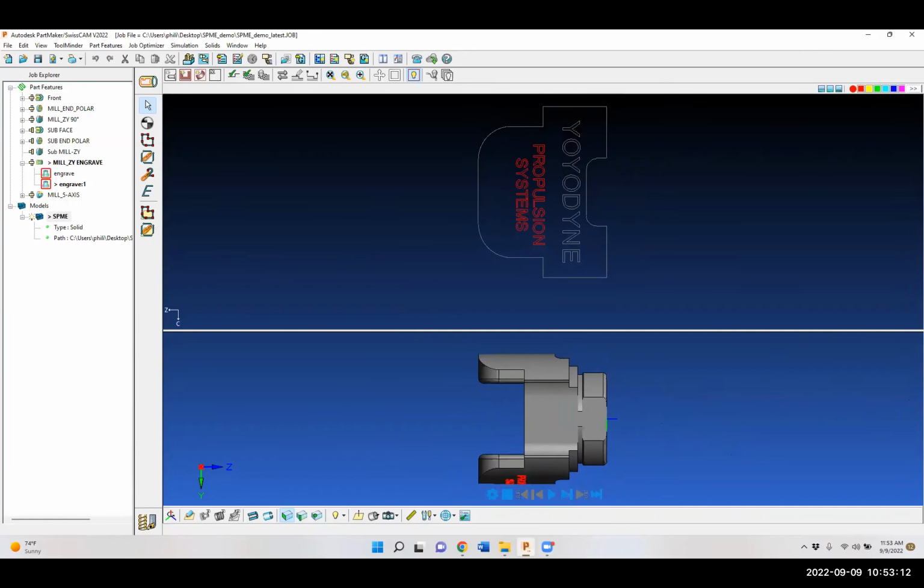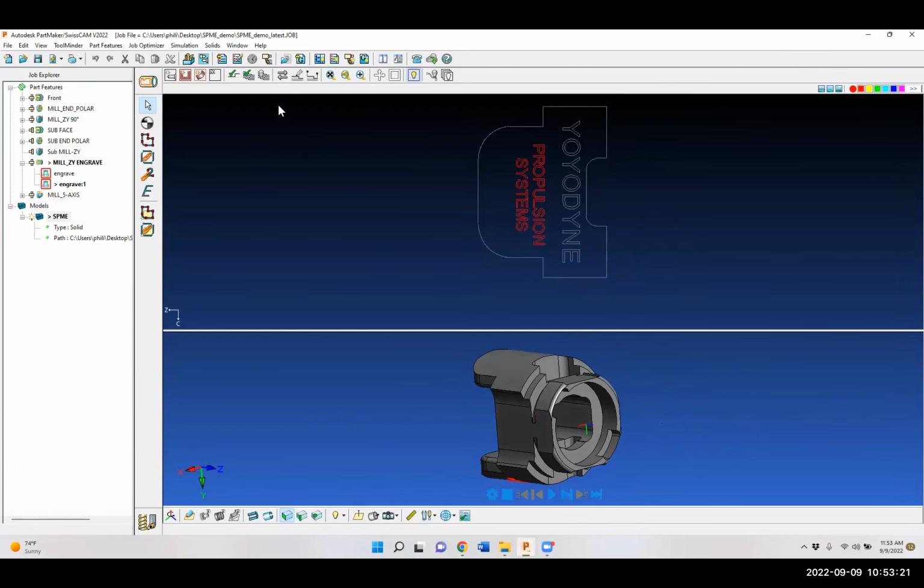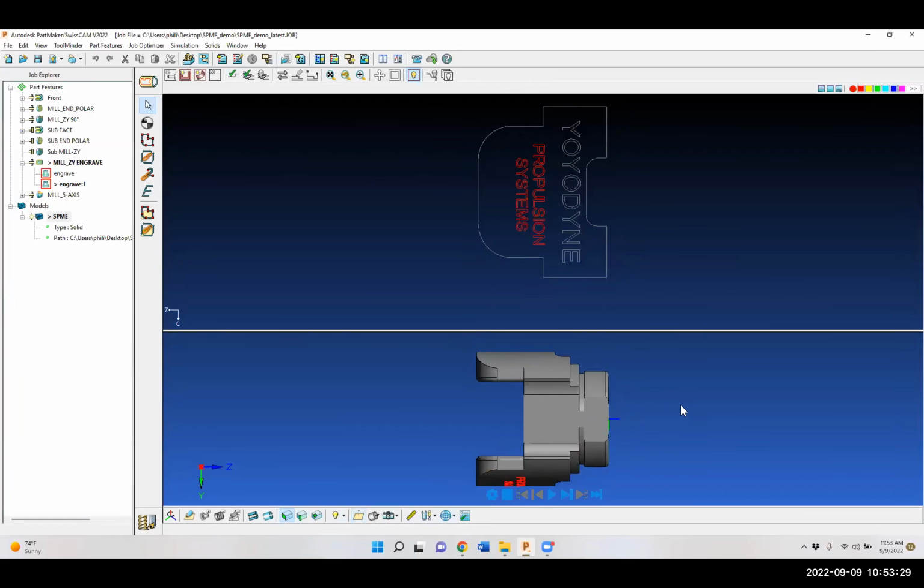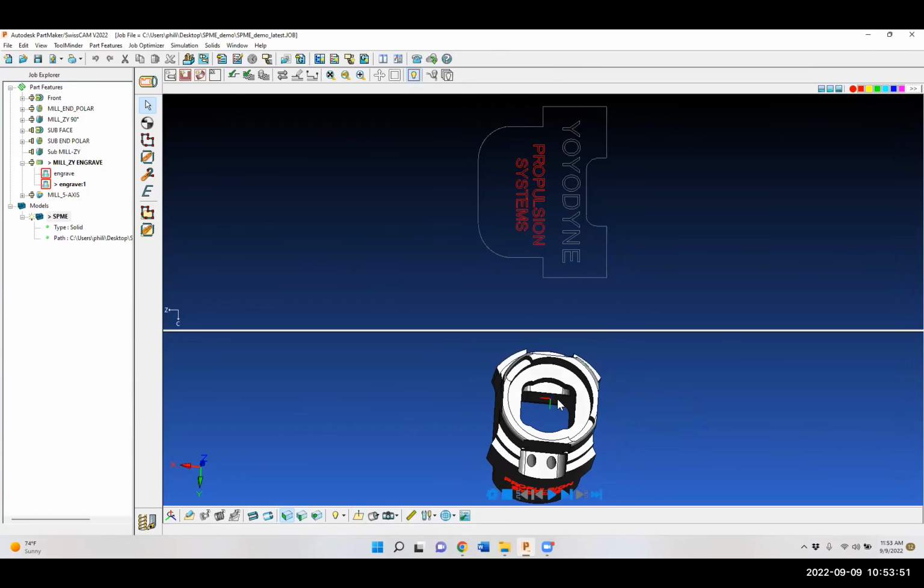Well, now I got a question. Yeah. When you were talking about the B-axis, whether you had to select global or local coordinates. Yep. I remember when we do that, we had to experiment. Yeah. So normally what you can do is you can call up your machine tool dealer and you can ask him how you set your 5-axis coordinates. And he'll tell you it's either a global coordinate from a pivot position or it's a local coordinate because you're using tool tip compensate, TCPC. I think it's what it is. Basically, you're creating a local coordinate. You're creating a plane with BC, XYZ, local to where the part is.